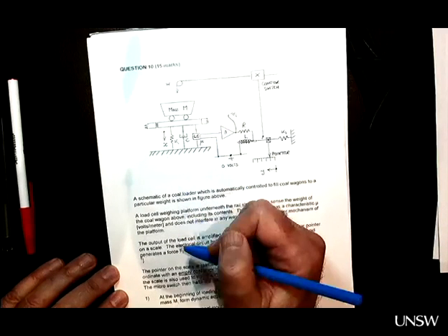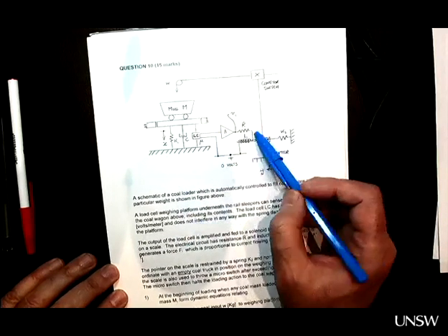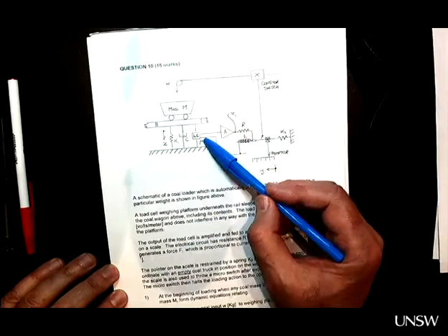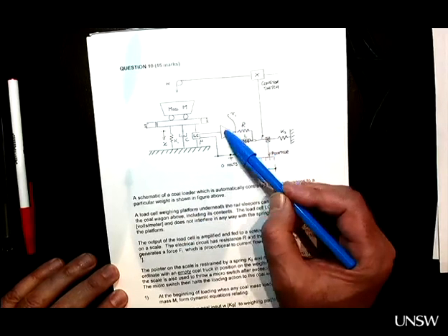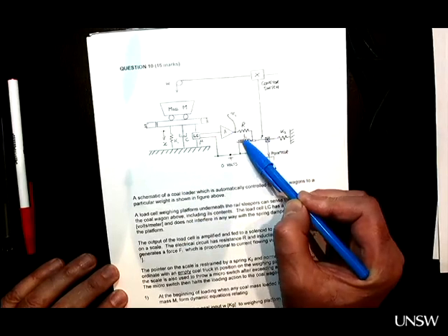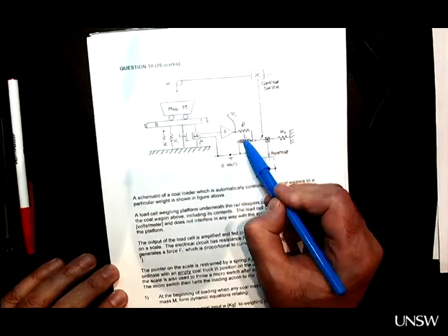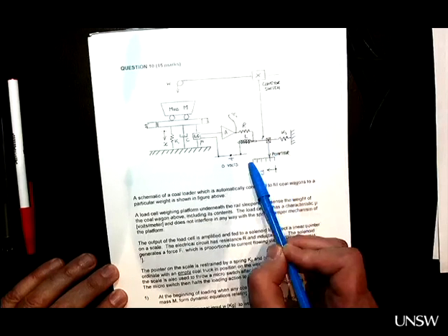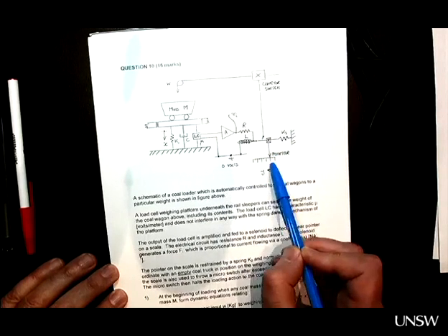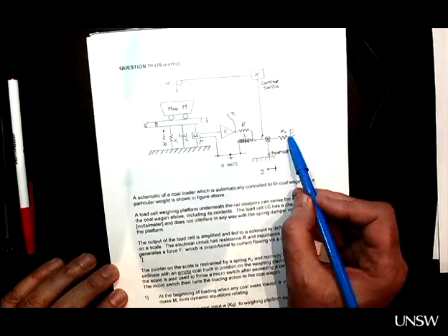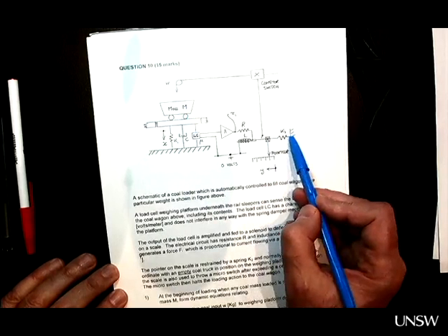The voltage generates current, obviously. So the voltage between these two lines generates current that goes through, first, the amplifier, then through the resistor, then to the inductive coil. The inductive coil generates an electromagnetic force which pulls the pointer. So the pointer is telling us how much coal we have in here. The movement of the pointer is balanced by this spring over here.